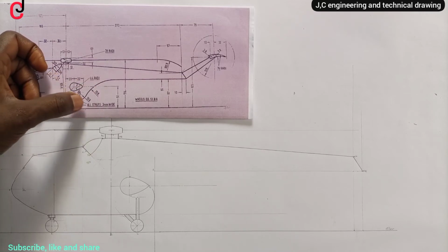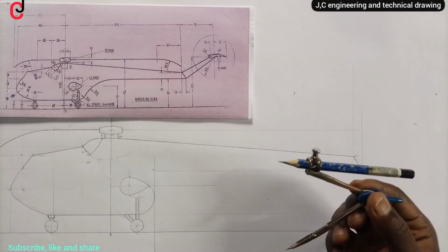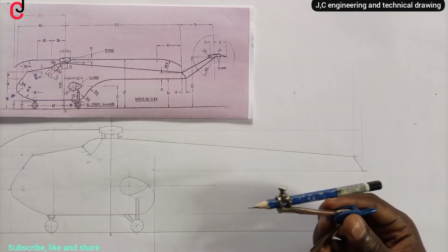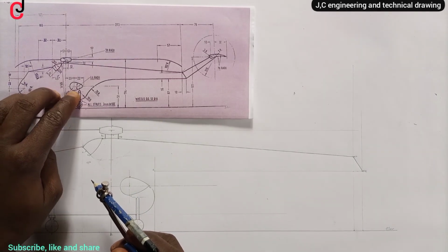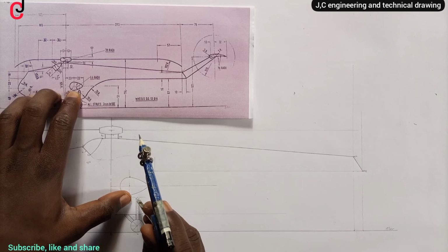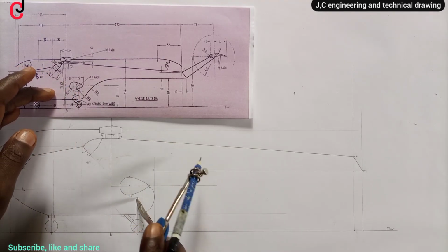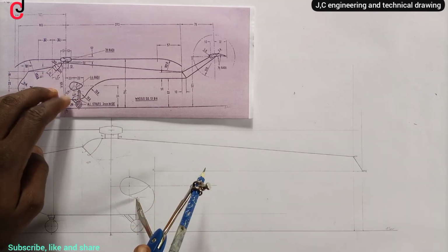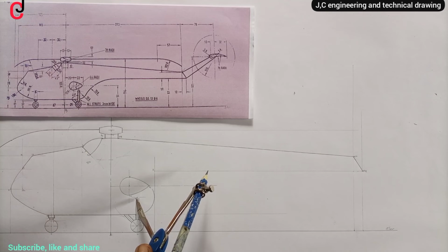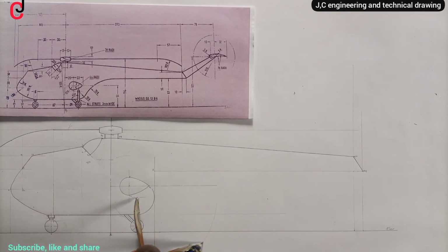We add 19 plus 70 millimeter, which will give us 89 millimeter. So place it from where our 19 millimeter progresses from, which is this point here. Then we'll scribe an arc with radius 89 millimeter.